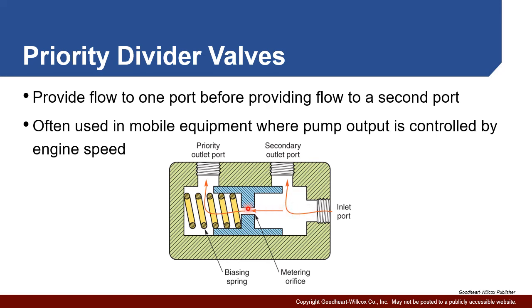What it's going to essentially do is also act as a regulator when we're dealing with internal combustion engines. So if we ever have higher flow, it's only going to get a certain amount out, and then any extra flow we're going to get is going to go out to the secondary outlet port, potentially back to the reservoir.